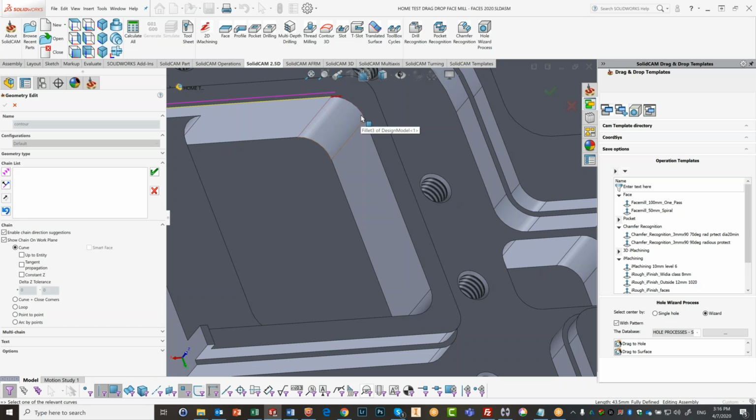But sometimes the parts that you are working on are imported parts. Parts that are imported, specifically parts like IGES, you may see this as one element, as one arc over here, but the IGES will see this as many small points. And if I try to pick that element, it won't choose it. It'll choose some point I picked over there, and that won't work. So in order for me to get an arc over here, I have an option called arc by points.